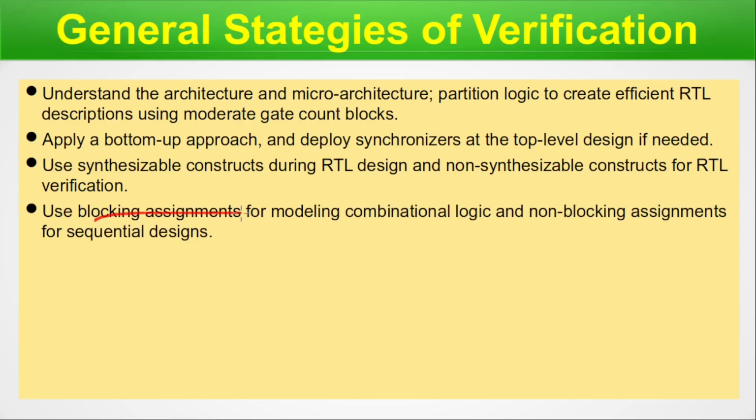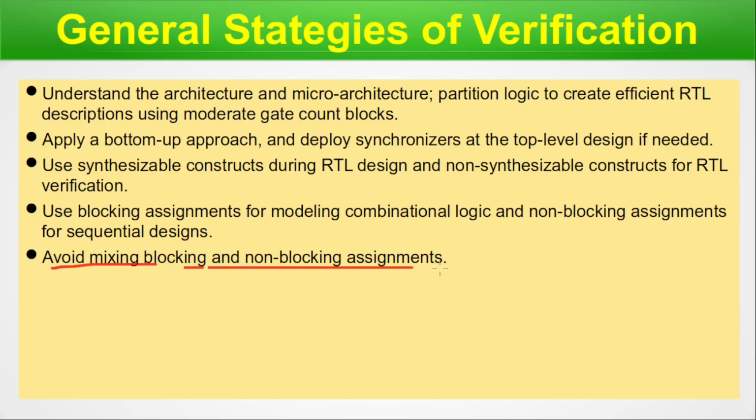Use blocking assignments for modeling combinational logic and non-blocking assignments for sequential logic. We have already discussed this in detail in the Verilog series, and the Verilog series now has a marathon, so you can watch it. Avoid mixing blocking and non-blocking assignments. This is a very fundamental thing: you cannot mix blocking and non-blocking assignments together, because in this point we have clarified that blocking assignments are for combinational logic and non-blocking ones are for sequential logic.